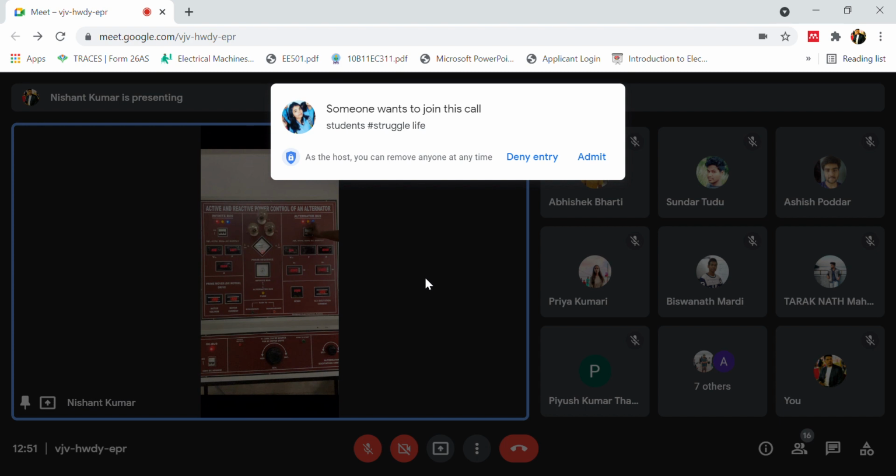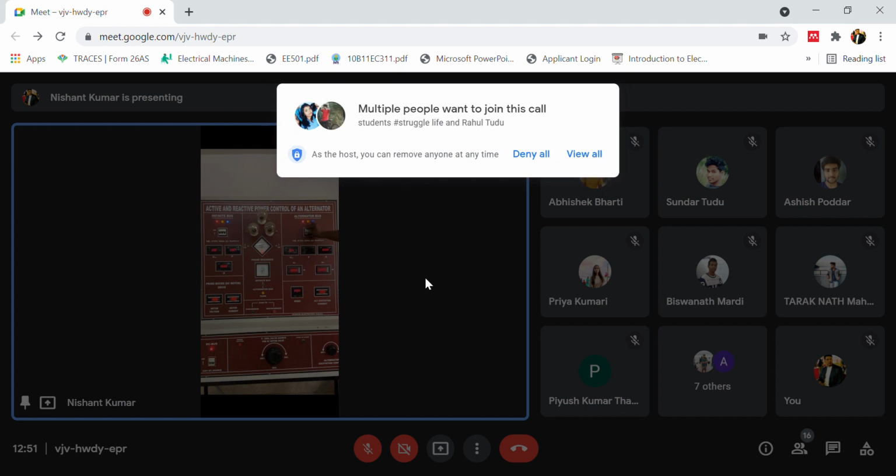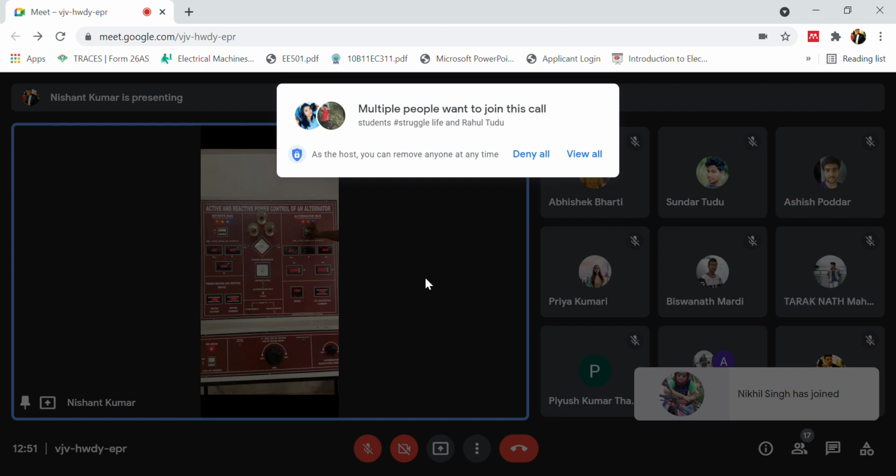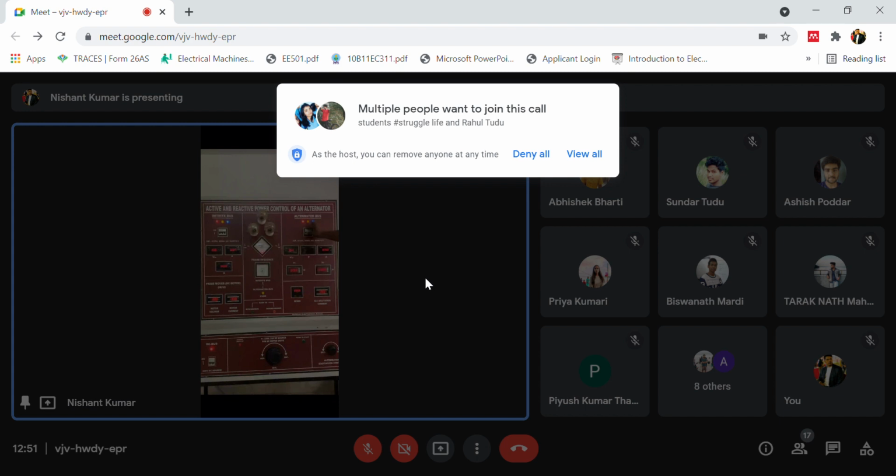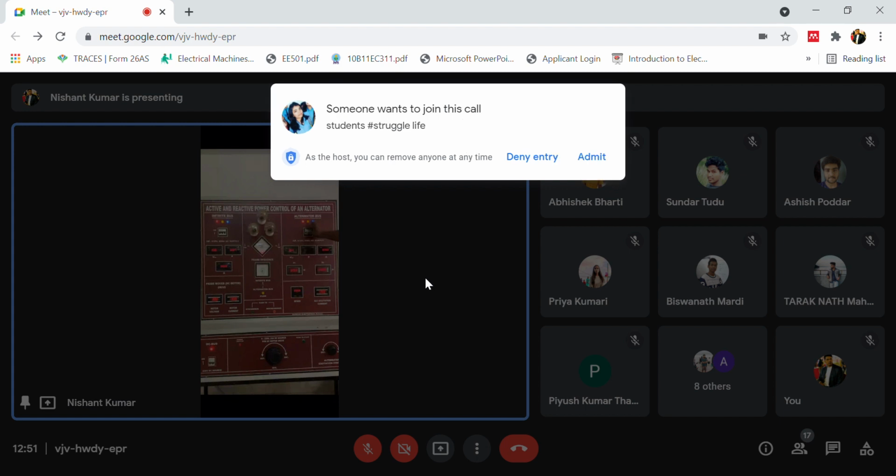Now when both are running at rated speed and the field excitation is being provided, there is one terminology that you will come across, or have come across, that is residual voltage or residual current. That would be seen whenever it is being rotated. Until you provide the field excitation to your alternator, it will not start generating. So now the entire process would be how to synchronize, what you have to see and what you have to consider. Okay, let's move ahead.